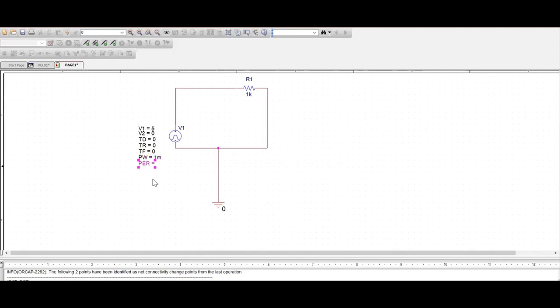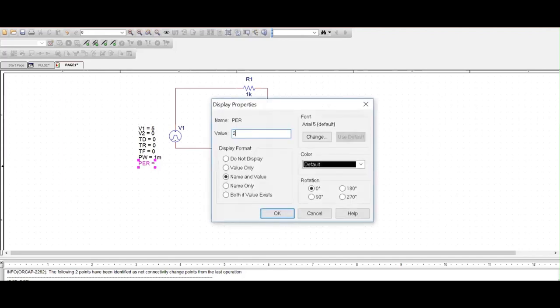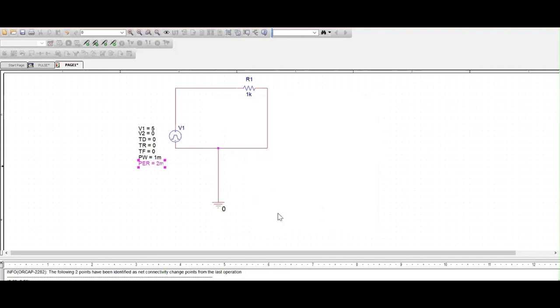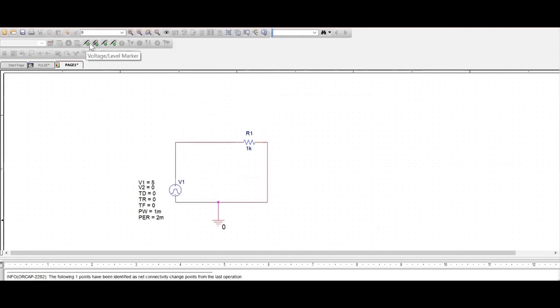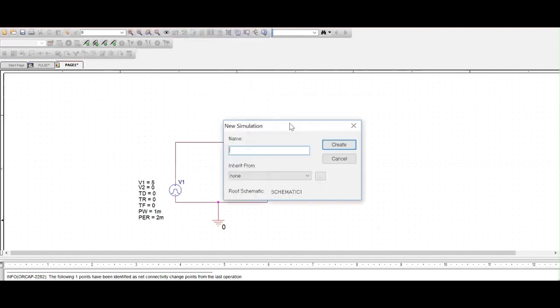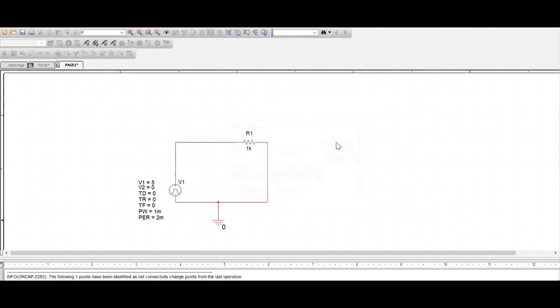And so for new simulation, we need to give a simulation profile, general circuit, and then let's connect the probe. I'm giving the probe here, and after that I'm giving it some few seconds. So for a running time, I'm going to give it 100 milliseconds if we want, but as the time period is slow here, I'm going to give 10 milliseconds. So, and then let's run this, and after that you can see profile is rising here.